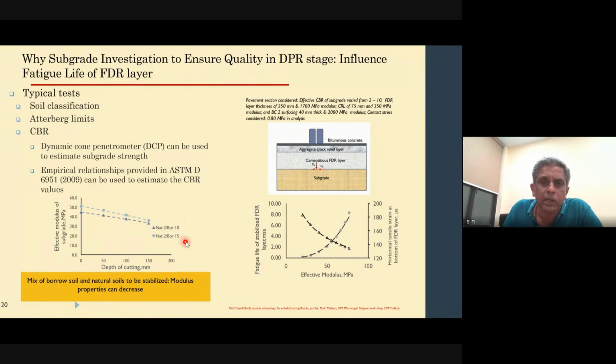Now, after doing all the mix designs, after making adjustments and getting to know how these things need to be mixed, what really matters is whether we are able to replicate a mix design onto my field. Simplest thing. It has got to work in the field, otherwise everything is useless. Now, I cannot take a risk in terms of constructing 5 kilometers and check if the processes work fine or not. An easier solution to address that problem is to build a trial patch, which has been done in all UP projects. Every single project had a trial patch.